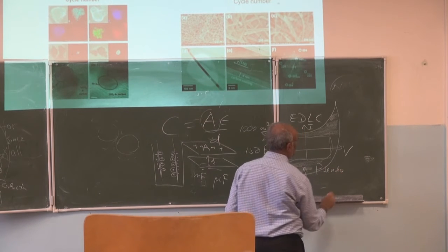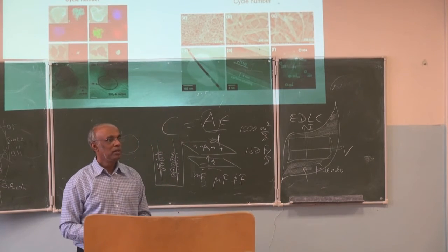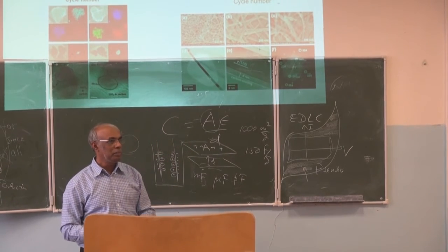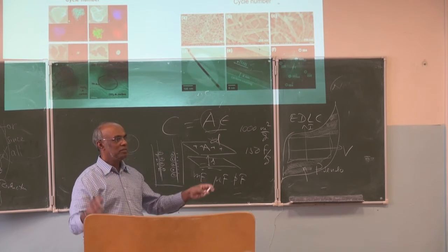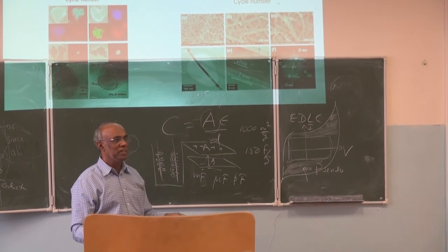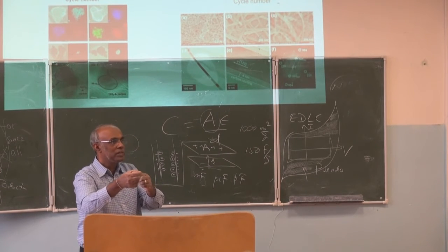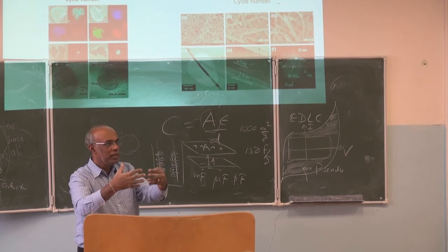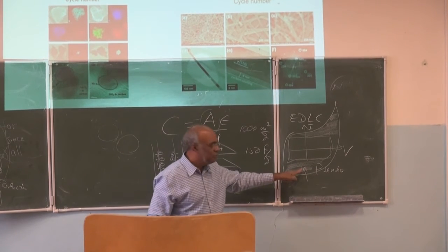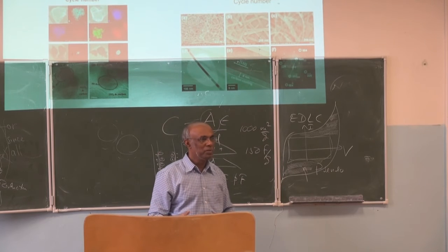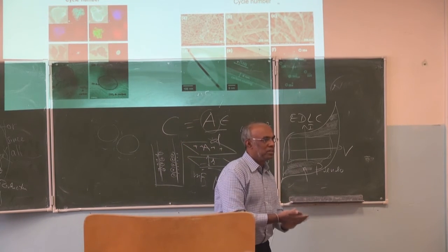So that will make your capacitance higher, like Alexei, he mixed this nanocarbon with some conducting polymer. Conducting polymers are donating electrons to the carbon nanocages, so that will make some conjugated system. So that's why we get close to 200-some farads per gram. I haven't finished that paper.